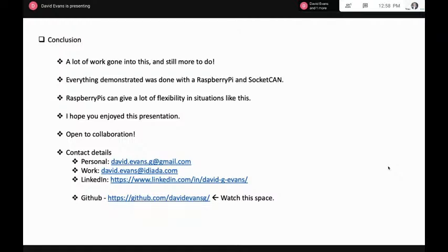So in the CAN segment application, which I'll make available, it uses that as your input. If you want to come up with a clever way of segmenting the vehicle speed value, all you need to do is implement that clever way of shifting around the bits and the bytes.